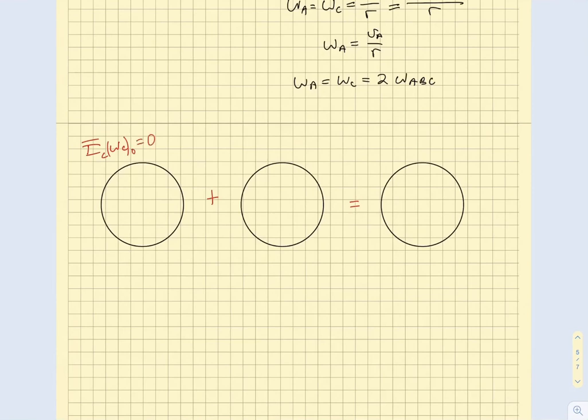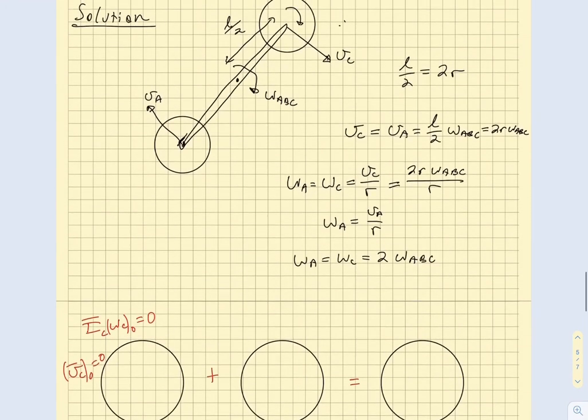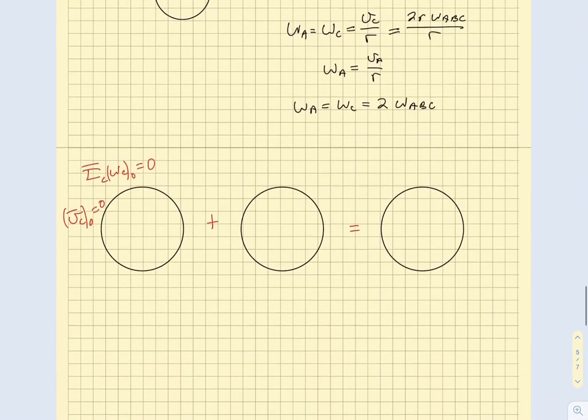So we're saying momentum state 1 plus the impulse should be equal to momentum state 2. Here we know the I bar, and we're doing gear C. So I bar C omega C initially should be equal to 0. And we know that V bar C initially is equal to 0 because we're at rest.